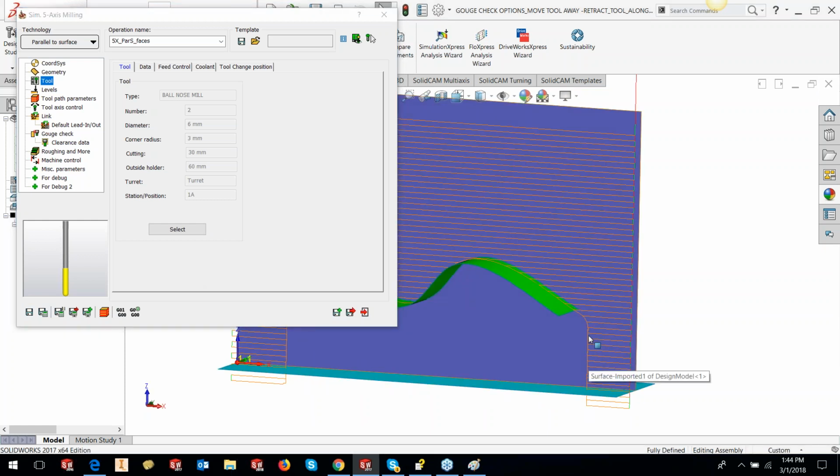It's just retracting straight. So the tool contact line, retract along tool contact line, will pull the tool out along the side face angle. If the side face is straight, it'll just pull it straight. If the side face has an angle like a taper mill, it will pull along the taper. Okay, it will pull the tool along the taper so that no more collisions happen.